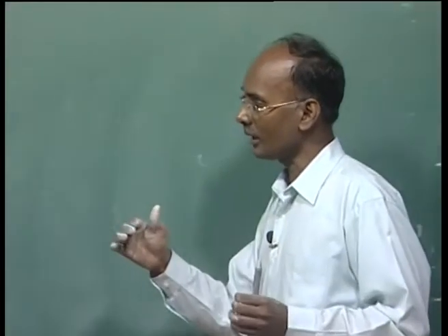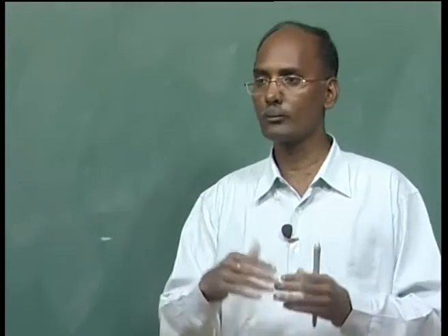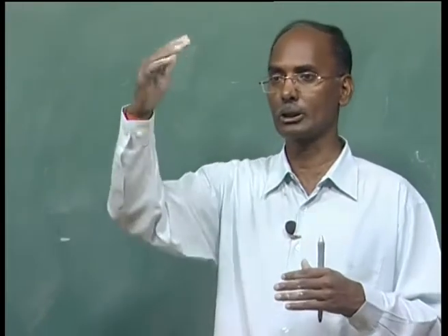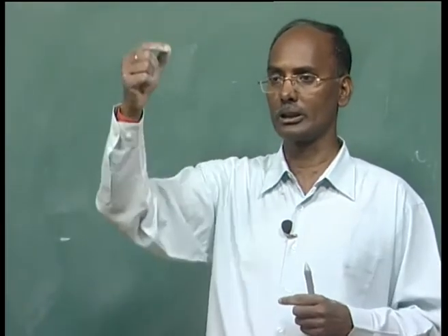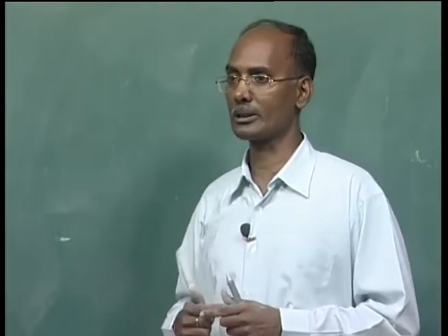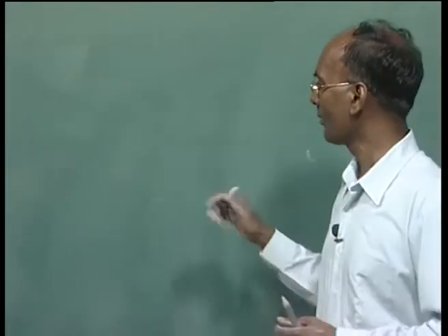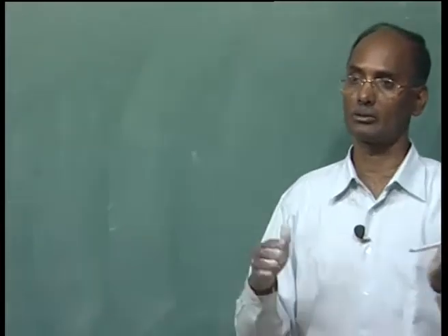Another one I already discussed, that is the saturation of the transformer. We have a huge current flowing in the primary side, with sudden jumps, and sometimes the current suddenly increases and there is saturation of the transformer, and due to this saturation we inject harmonics into the system, and they are not the characteristic 5th, 7th, they are uncharacteristic harmonics. So the harmonics generated by the transformer are not characteristic harmonics.